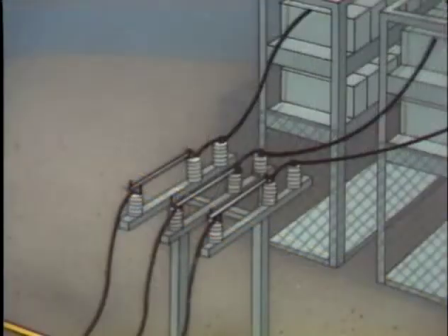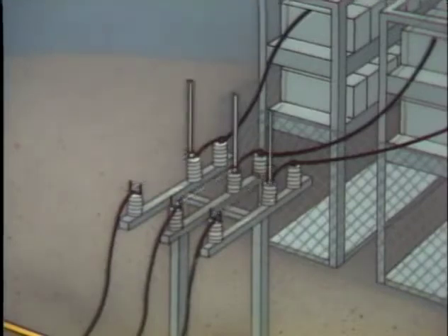In this example, 3 single-phase disconnects are opened to provide a visible break between the source of energy and the bank. The actual switching devices that are operated and the sequence in which they're operated varies with the design of the substation. Normally, a capacitor bank is switched out only after getting permission and detailed switching instructions. Then, after the capacitor bank has been de-energized and isolated, it's good practice to test the capacitor bank for dead.